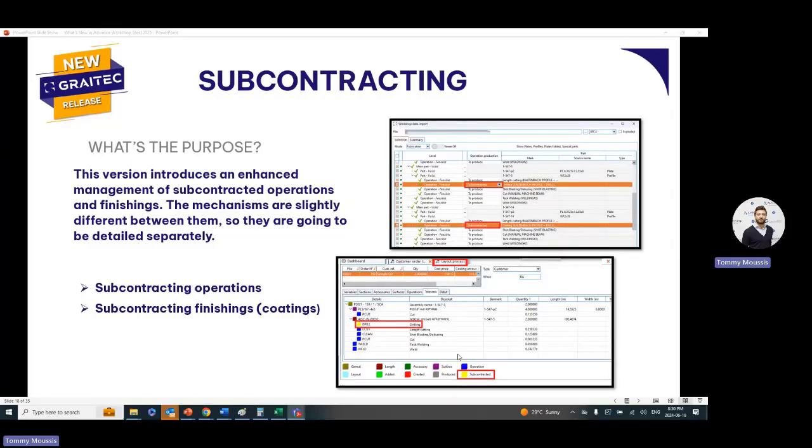In addition to that, we can edit the production assignment tree to automatically subcontract certain types of operations, whether it be to plates or bar elements, or whether it be just a simple operation like drilling. Every time there's a hole that needs to be cut on a plate, we can subcontract it automatically.